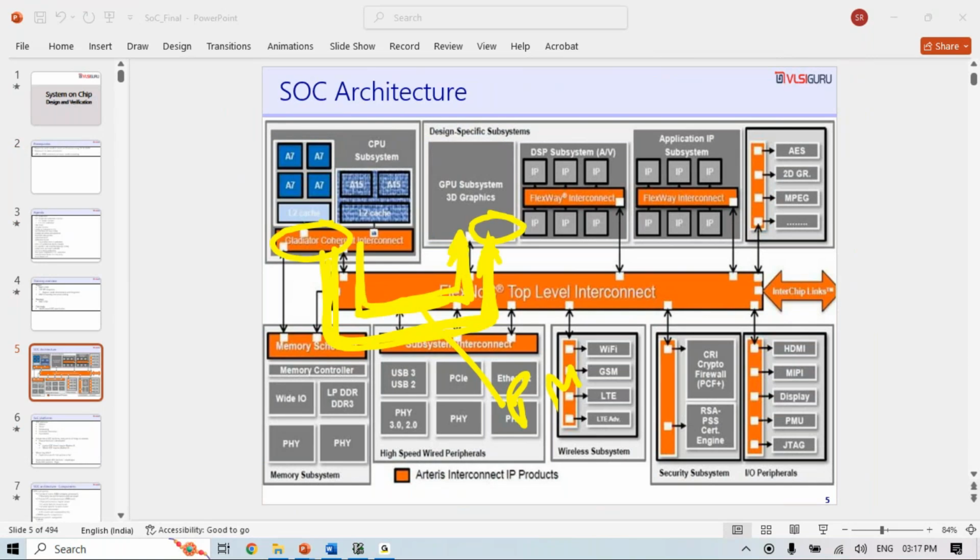So whatever I was telling, the 256 byte flit information will be carried on the main band. For example, when you are sending this information, you need to give power management acknowledgement, right? Sometimes you want to do power management state transitions and everything. That information will be carried through the sideband channel, and also any parameter negotiations that have to happen will be done through the sideband. It is done so that the overall link performance will not be impacted, because if, during the traffic, you start doing some sideband activities, the main band link will get impacted. So they have purposefully divided this into two things.